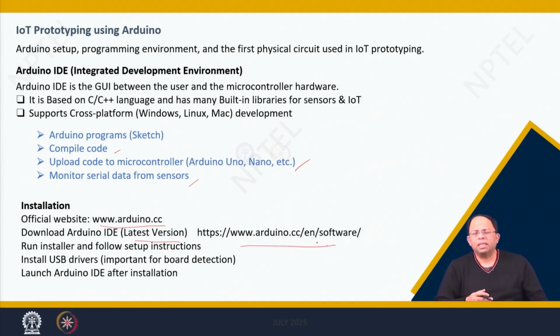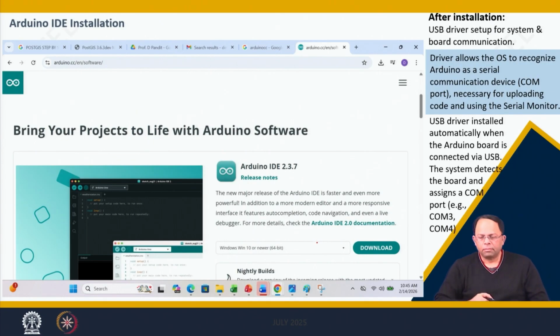That means as soon as you connect the board, it requires some drivers to create that interface between your computer and that particular board, right? So without those drivers it will not work, and that has to be there. And then we launch the Arduino IDE after installation, and then we can start writing code and pushing code to the microcontroller.